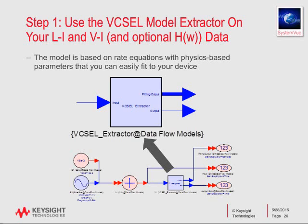The good news is that as part of our optical setup inside of System View, we have produced a VCSEL extractor module, which you can put into a simulation, as you see here. Not a very complicated thing at all, very simple in concept when you get down to it, which allows us to take in measured data, and from that measured data, extract the appropriate parameters in an automated way.